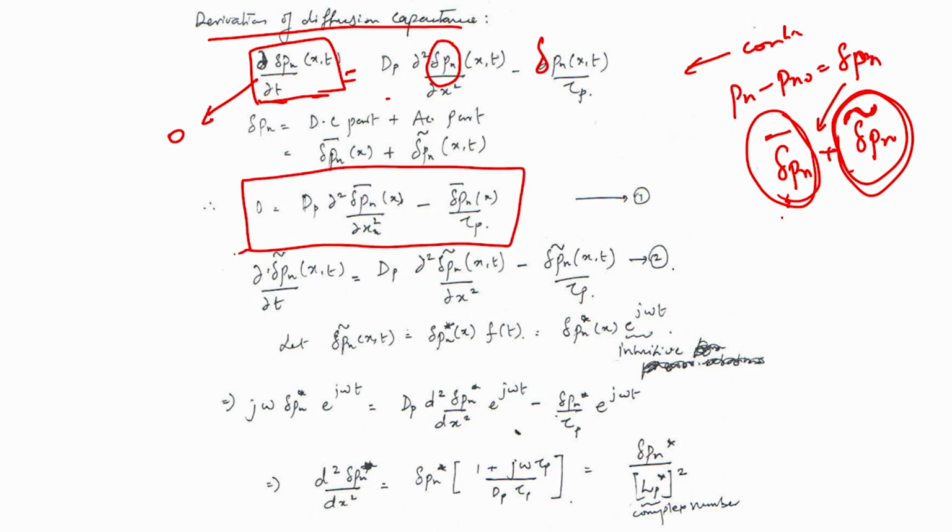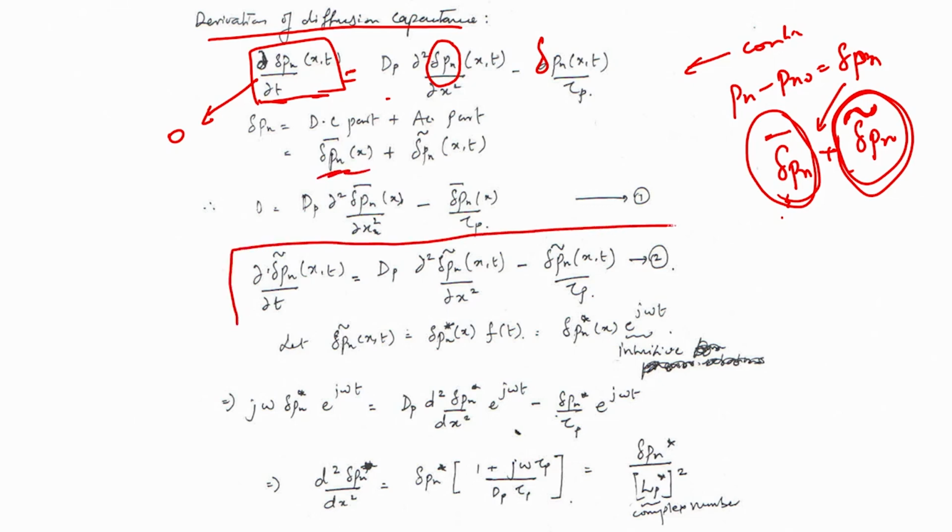That is what we used for the current, there was no fluctuating voltage component there. But now since we have a fluctuating voltage, the AC part alone, that is if we get rid of the DC component and take only the AC component, we find that this is the continuity equation of interest. There is a transient, there is a diffusive term, and there is this recombination term, okay. So now how do we solve this continuity equation?